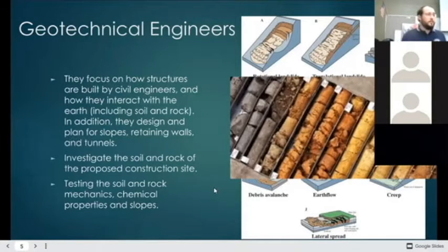Even when they go out, the concrete is very different from a sidewalk to, let's say, a dam or a building. The concrete is different at those different times. So whenever you pour concrete, you're supposed to have a geotechnical engineer have the cement truck pour a couple of samples in like little tin cans, and they test those samples. They'll test them as soon as it's rock solid, which might be in about 24 hours. They'll test it, then they'll wait another 7 days, because concrete, the longer it sits, cures harder and harder. So then they'll test it at 7 days, and usually I think they test it again a month later.